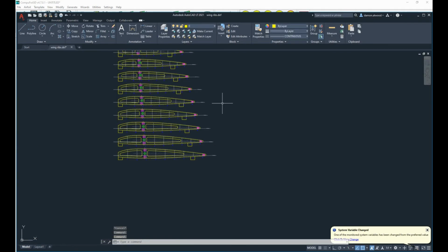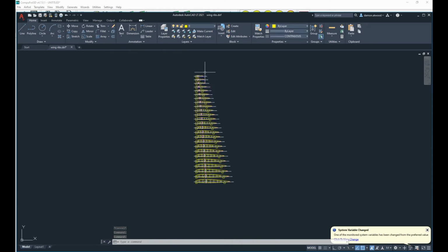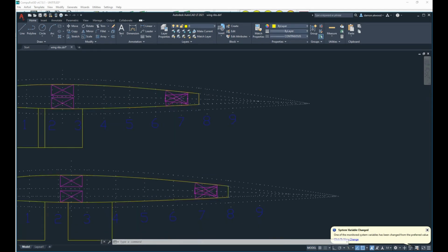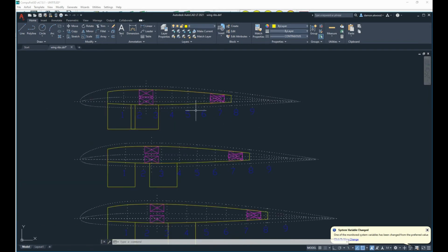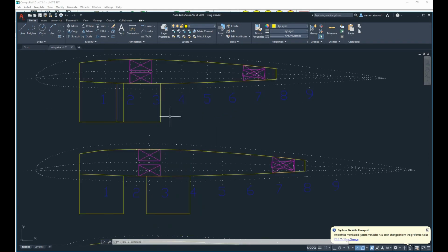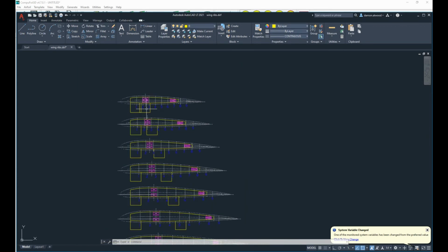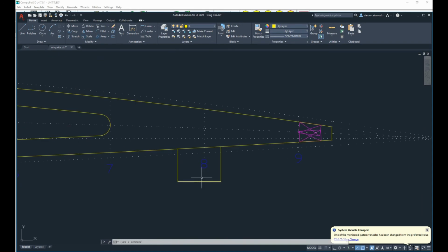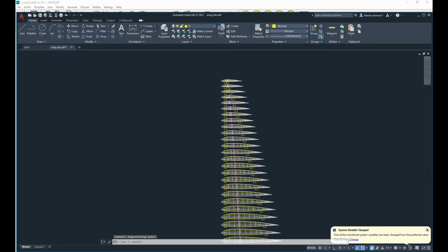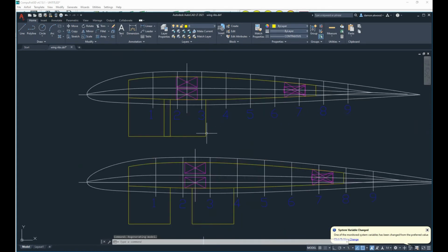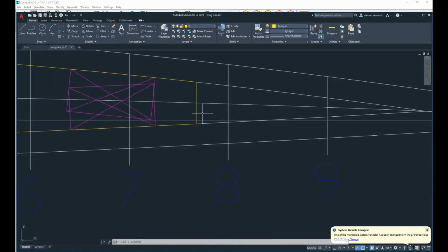So now that we're looking at this now in AutoCAD as a DXF. And if I go up here to my wingtip where the aileron would be, now look, I'm only going to do one rib right here, okay? But he needs a cutout right here of what he's going to do with his ailerons. And I will go back in and adjust the... if you notice, I brought the rear tab in enough to clear the aileron, but at the wingtip, the tab's in too far. But I would leave that. I'll just move that manually in AutoCAD. But let's go in here right now and look at this.